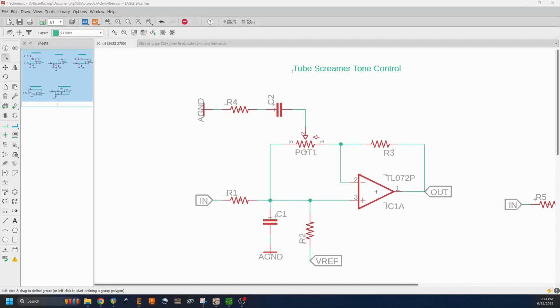But with an active one, we can actually boost signal that we want while simultaneously getting rid of signal that we don't want. And another benefit is that an active tone section will buffer the tone section so that we don't have tone suck, and it will give us a low output impedance so we can drive parts of the circuit downstream without loading them down a lot.